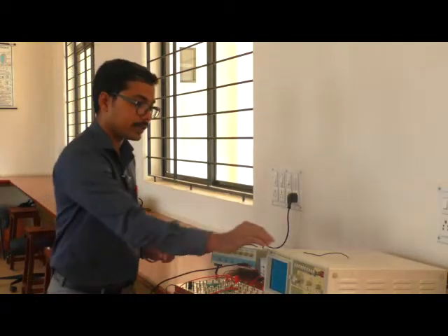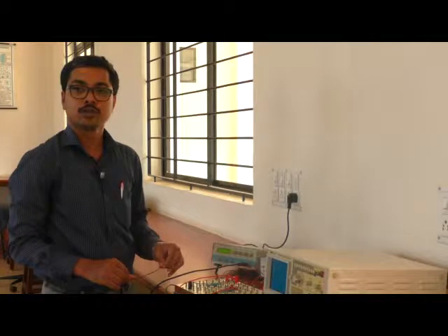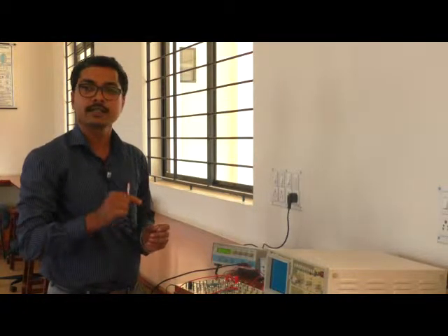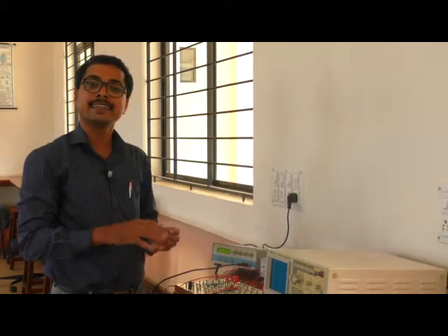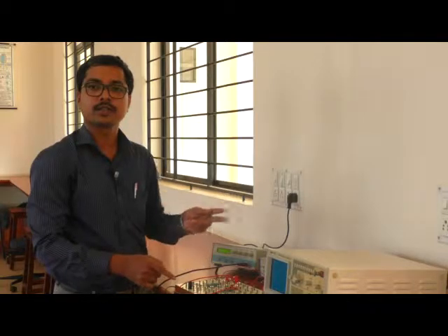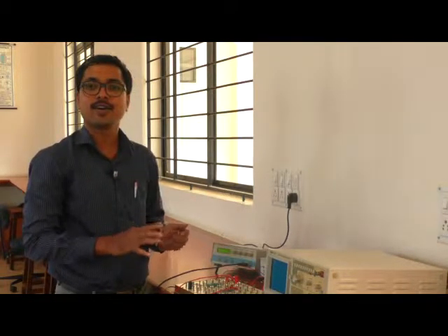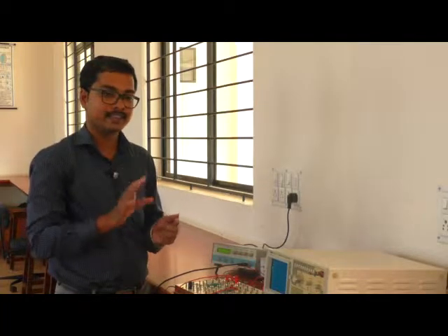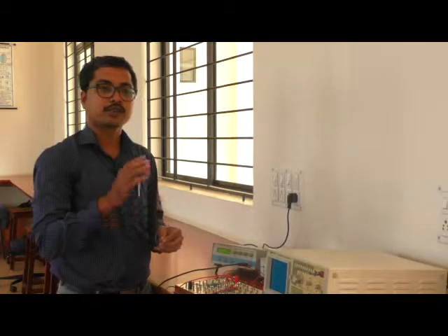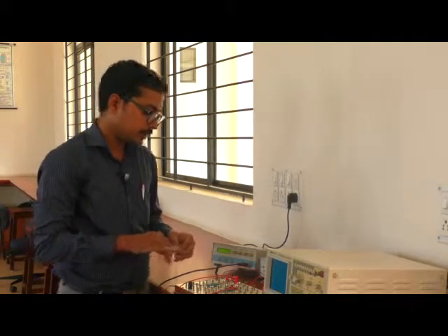There is one connection required to bring this circuit to the closed loop format. If any part of the output is brought back to the input, it is called closed loop, and its gain is controllable. If no path is established from the output to the input, it is an open loop configuration, where the ideal gain is infinity. But we don't have infinity, so we range it from 10 raised to 4 to 10 raised to 6. That is the gain of the open loop op amp.